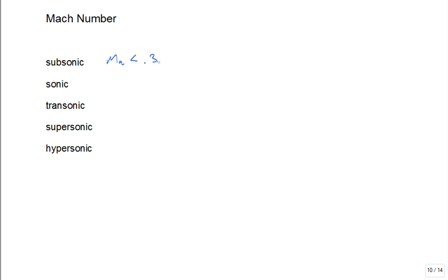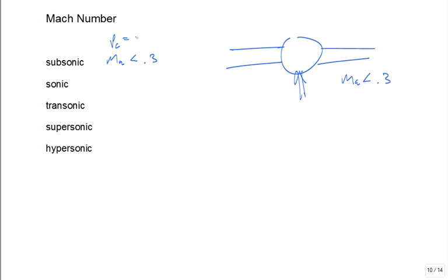So some people think, oh, I got air flowing in this system, and over here I put it through a compressor, and now it comes out. But because the Mach number is still below 0.3, the compressible effects of the gas must be negligible. No, you just went through a compressor. You just beat it up and boosted the pressure. This is more of at constant pressure. If the pressure's not changed because of a compressor, if it's constant pressure, so to speak, in a flow system, if you're not going very fast, if you bring it to rest, the compressible effects are negligible if you're below a Mach number of 0.3.